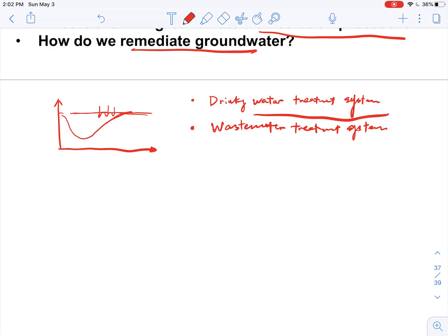there are not a lot of procedures being involved like the drinking water system because there's a lower requirement. For drinking water, we have to guarantee that it's safe. But for the wastewater, we're not drinking that. It's just pumping back into the environment. So there can be some BOD left in the water there. So there are primary treatment and secondary treatment. And secondary treatment is required by the federal agency. More specifically, a major type of secondary treatment is the activated sludge process. We introduced how we can design those processes.